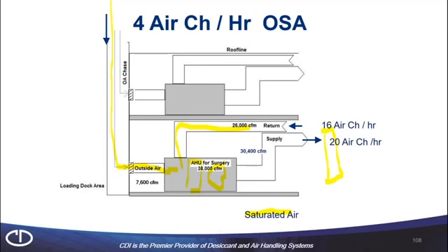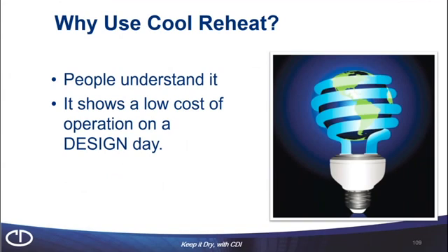At this point, I'm going to ask you, why was it that we're trying to hold in that room below 60% relative humidity? That's because bad things grow above 60% relative humidity in the room. If you were to take that same surgeon up and have them look inside this air handler and look at this 95, 96, whatever percent relative humidity airstream until it gets reheated, what would they see? What would they swab? So we would submit that if you're going to hold the room to that condition, 60% or below, that we really should be holding any air that's in this duct below that condition as well.